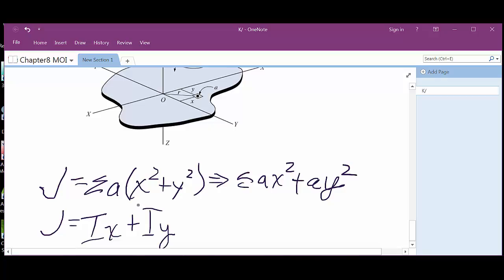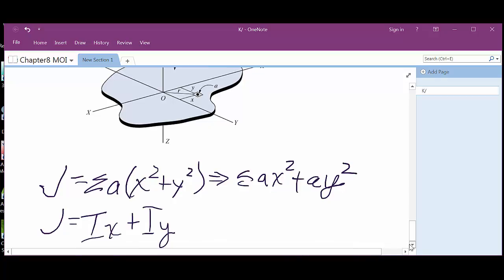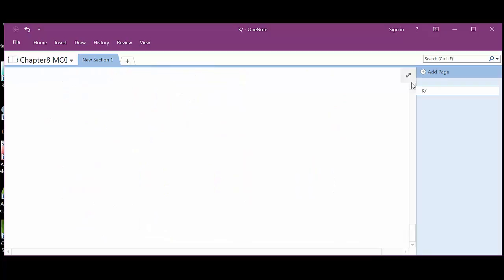So when we look at this problem, we've got that hollow shaft, and this is where we could remember we were talking about the drive shaft the other day, where we could prove out that we get better results from that large diameter skinny cross-sectional area as opposed to the thicker.